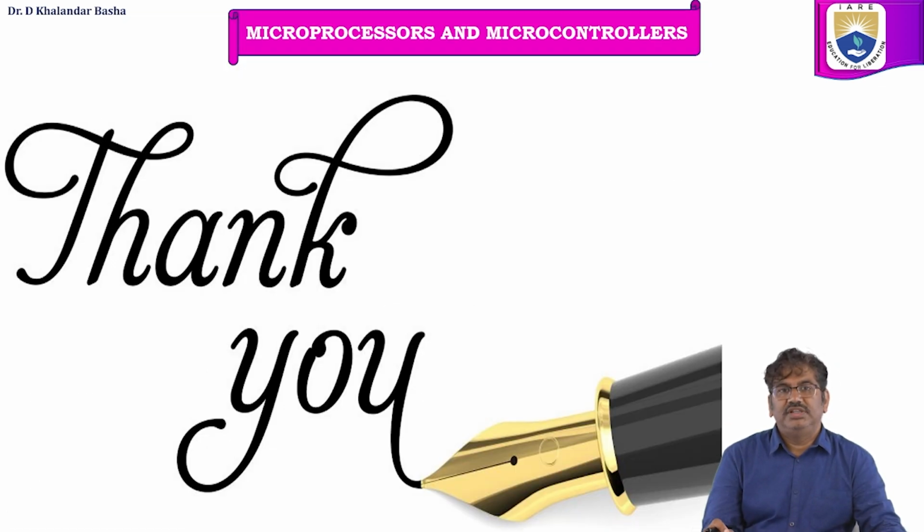So in this session we have discussed the machine language instruction formats. In the 8086 processor, the instruction formats may vary from 1 byte to 6 bytes. In these instructions, we discussed the various fields we have, and how to recognize or write the equivalent opcode for any instruction depending upon the register, its size, whether it is sign extension or not, and what the addressing mode is. Depending upon that, we can write the equivalent opcode for any instruction.